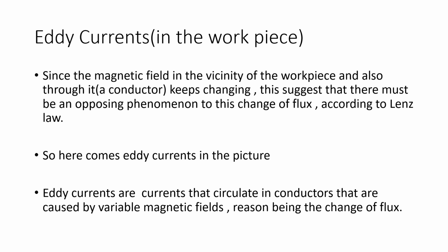Discussing the eddy currents generated in the workpiece, since the magnetic field in the vicinity of the workpiece and also through it keeps changing, there must be an opposing phenomenon to this change of flux according to Lenz's law. So here come eddy currents into the picture. Eddy currents are currents that circulate in conductors, caused by changing magnetic fields, the reason being the change of flux.